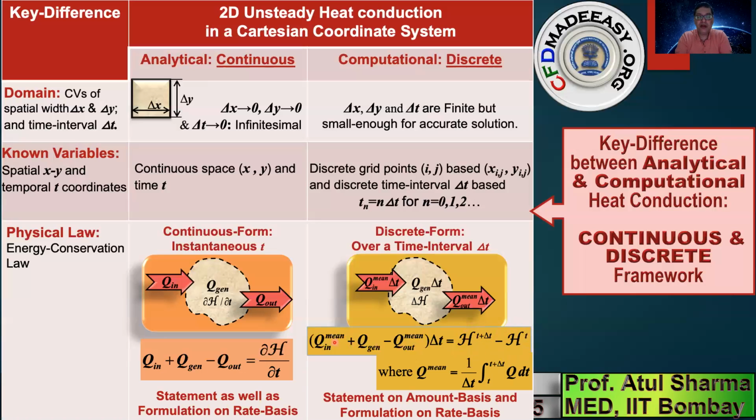Whereas the rate of heat transfer, note that with respect to time, is like a path function. So the amount of heat, which we had expressed in terms of rate of heat transfer, since it's a path function with respect to time, we have presented like an integral. I also want to highlight that in thermodynamics, you never use any symbol for rate of heat transfer. Although I am using a statement borrowed from thermodynamics, where the statement is on an amount basis, the symbols which I am using here are the symbols that we have seen in the heat transfer course.